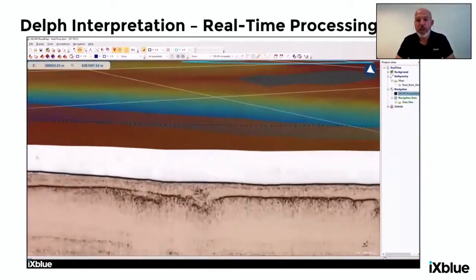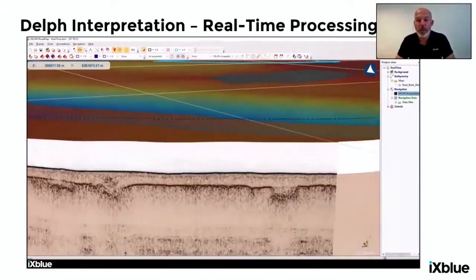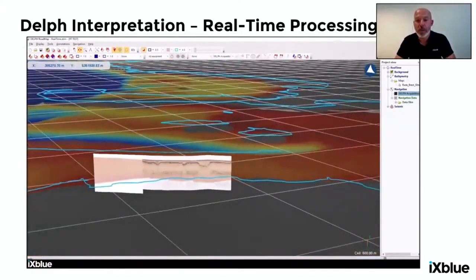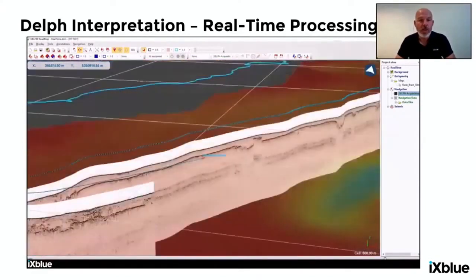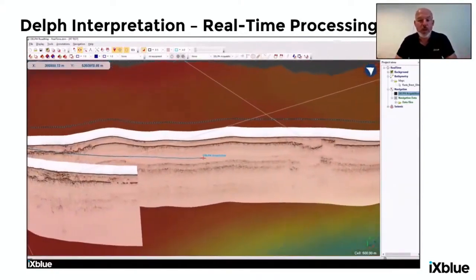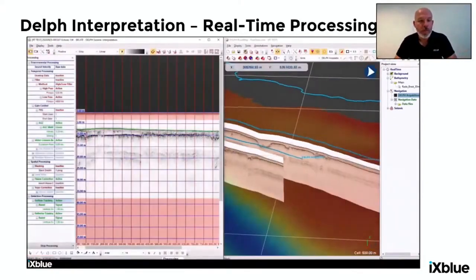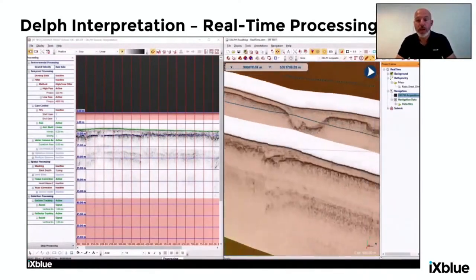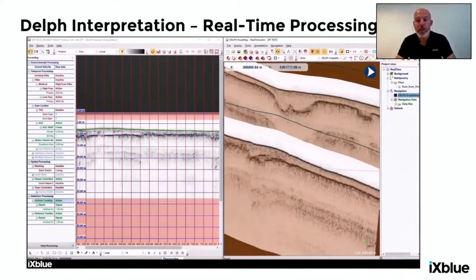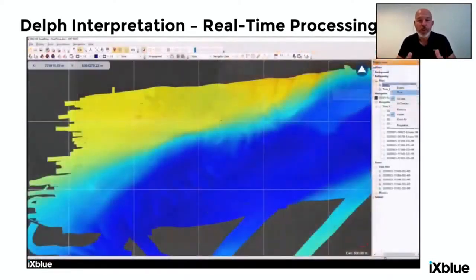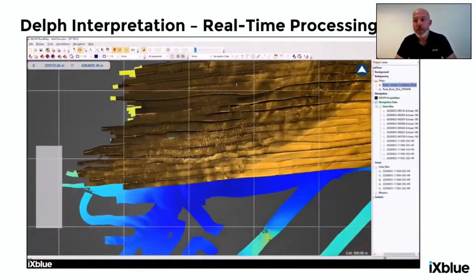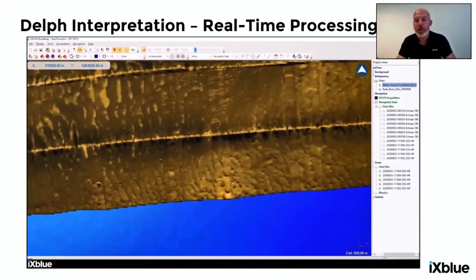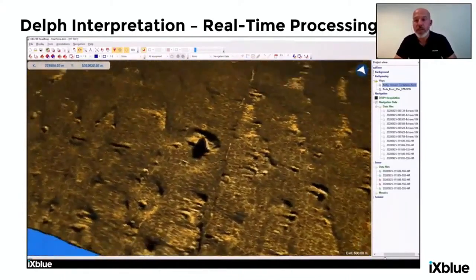This also provides an immediate availability of data for QC, so when the vehicle comes back, you can directly look at the processed records and maps, so the QC can start instantly without waiting for all these initial stages of data processing. On the field, you can also, on a crewed vessel, quickly plan core locations and grab sampling, etc., because all the information appears georeferenced. Same thing, if you see some buried features on the sub-bottom, you can spot them and re-inspect them or do closer, shorter line spacing to inspect them.